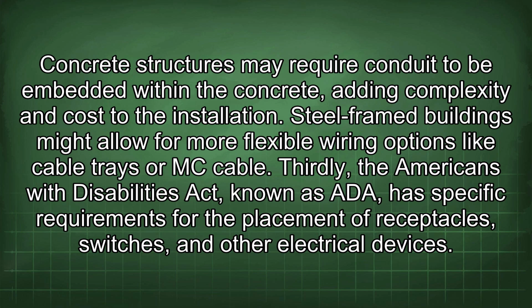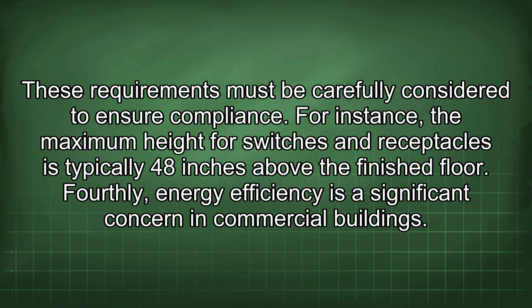Thirdly, the Americans with Disabilities Act, known as ADA, has specific requirements for the placement of receptacles, switches, and other electrical devices. These requirements must be carefully considered to ensure compliance. For instance, the maximum height for switches and receptacles is typically 48 inches above the finished floor.